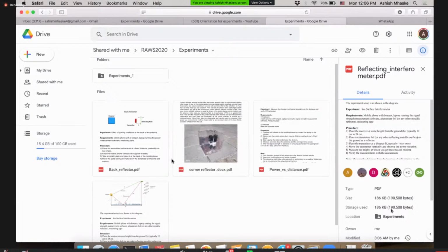Yes, that is again an important point. Whenever you are in the measurement mode, try not to create any disturbances by moving around the setup, or by moving your hand. These devices are actually very sensitive. Their noise floors can go to minus 90 dBm, so any small movement might change your measurements. Try to avoid those things. It should not affect very much, but it will give you better results.